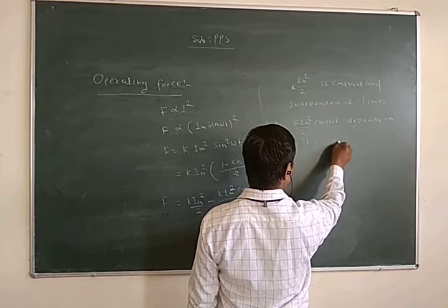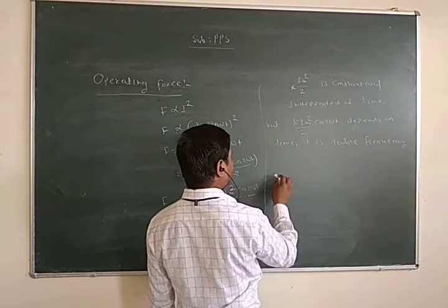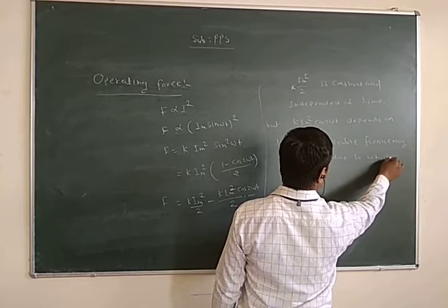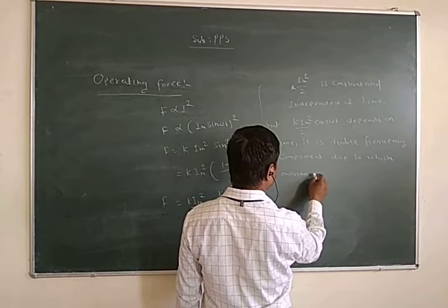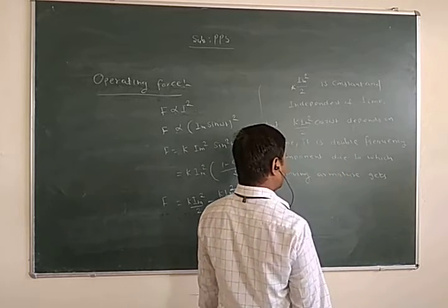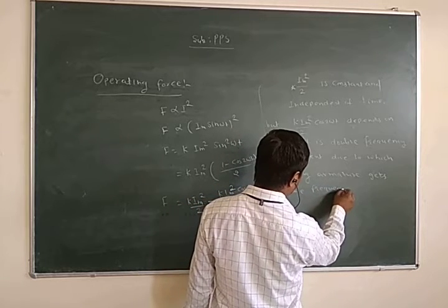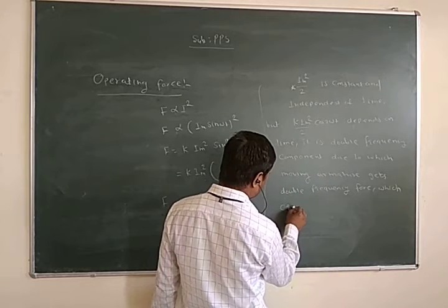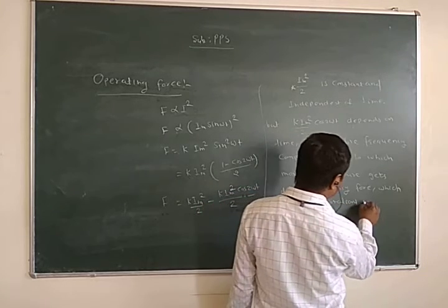It is the double frequency component, due to which the moving armature of the coil gets a double frequency torque, a double frequency force, which creates vibrations in the armature operation.